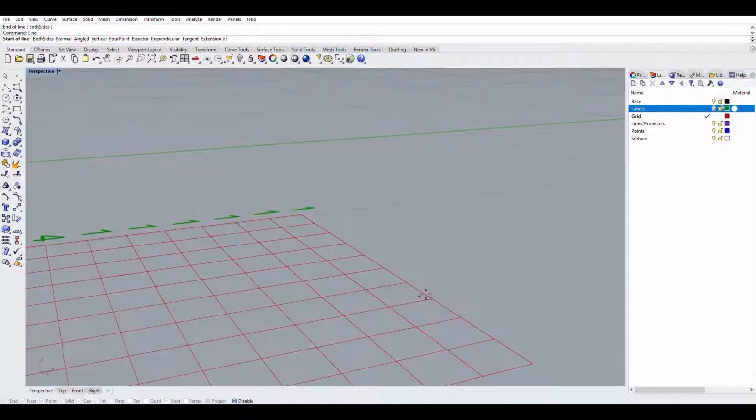But again, I'm gonna go to my line tool and go into, take my grid snap off. Right here. This guy. So right now, I can't really control in the Z direction. You can shift in other directions, but I want to control click right on my point, and that's holding control and clicking. So then I can actually do my heights.